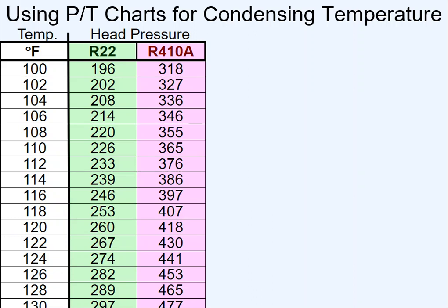I can't possibly remember all the pressures at every temperature for every refrigerant that's out there. My gauges have 60 or 70 refrigerants, and there are probably a lot more than that being used in systems out there. So there's no way I can remember all that. But if I know theory, and I know that at this many degrees my gauges should read this many degrees, I don't care what the pressure is. I just need to make sure that I'm on the right column, reading the right refrigerant, and that my temperature's right. As long as the temperature's right, I don't really care what the pressure is.